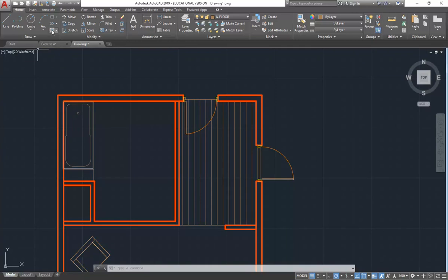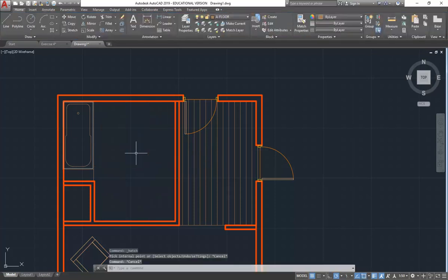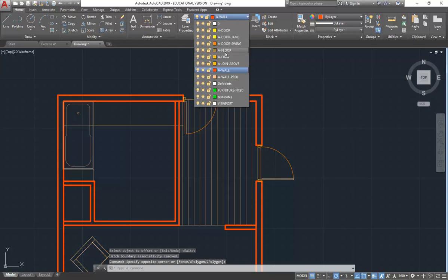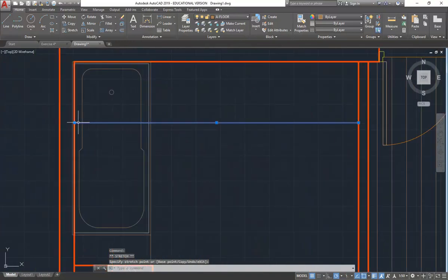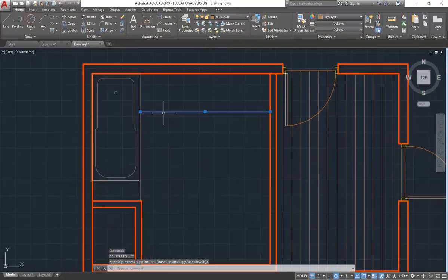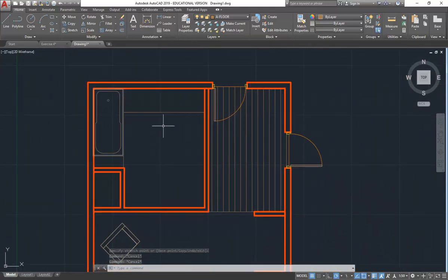So now, if I go to do my hatch, you can see it easily goes around it. So really you just need the, well, I'll do the next little bit. The vanities, I think they're about 600, so you can offset 600 from this line. I'll just change it to my floor layer, even though there should definitely be a bathroom layer for all those things. Trim the line back to the bath. And now that's ready for the hatch, except I need the WC as well.